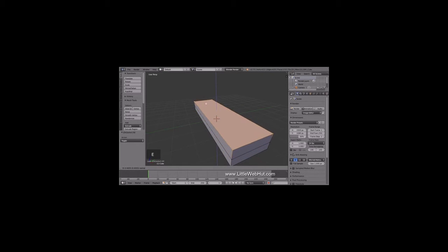You can see it extrude if you move your mouse. We're going to extrude to the same position as the original vertices that we selected. To do that, just click the right mouse button. Our extruded vertices should now be the only vertices that are selected, so let's scale them on the x-axis. So press S, then X, then 0.95, then Enter. Now scale it on the y-axis by pressing S, then Y, then 0.8, then Enter. Now we're going to extrude downward, so press E, then minus 0.2, then Enter.